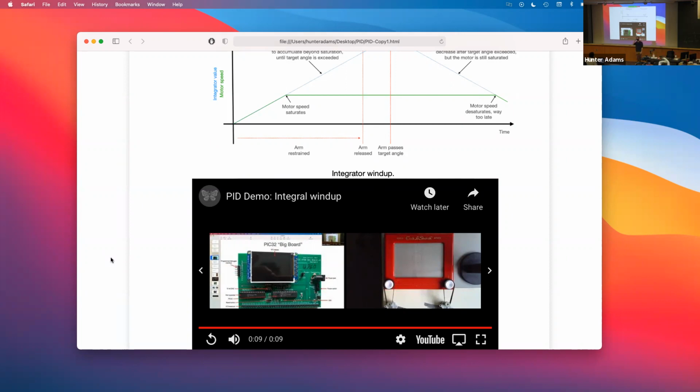Now multiplying by 0.9, uh-oh, that sounds like floating point. Well, let's see, you could shift by 1. That's multiplying by a half. You could shift by 1 and then add shift by 2. That's 0.75. You keep doing that and get arbitrarily close to 0.9. Do it a few times, get like 0.82 or something.